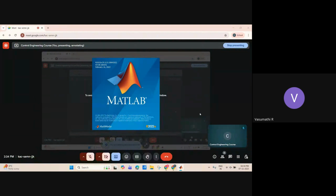Okay, this is my transfer function, right? S square plus 6s plus 8 into S. Now I'm considering K equal to 1. We'll change K and see. The keyword to plot root locus is rlocus in MATLAB. Just define your transfer function.